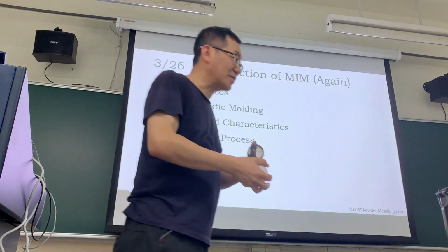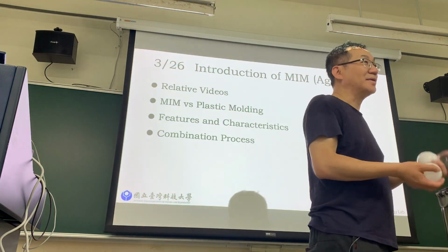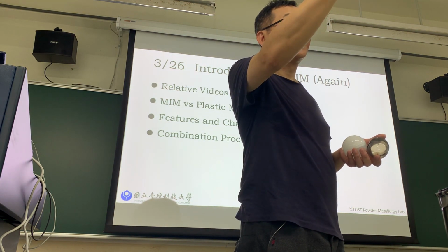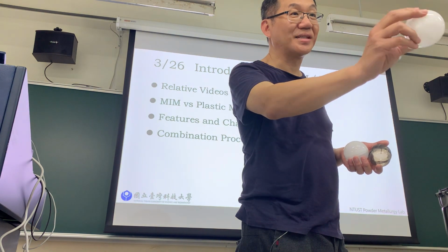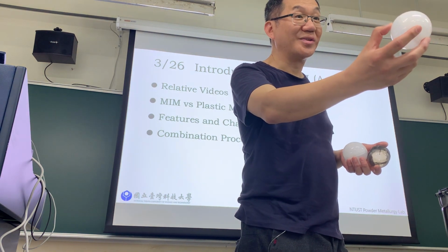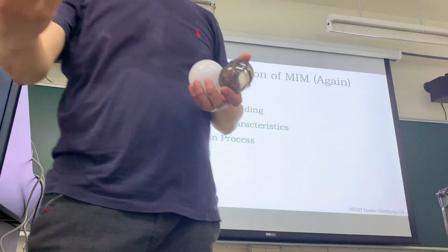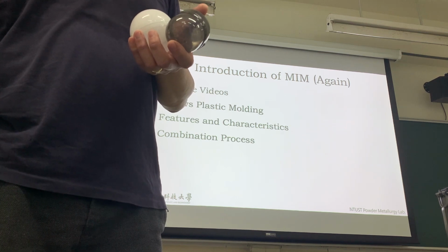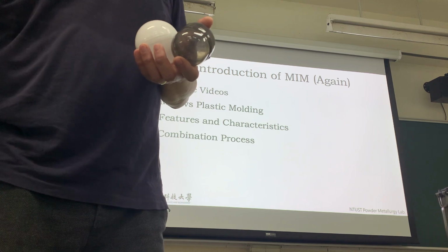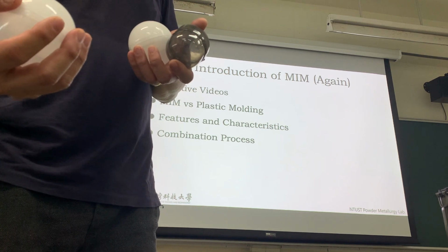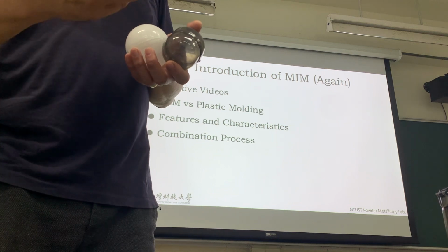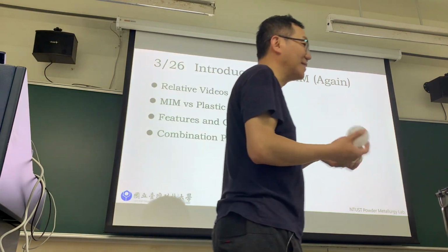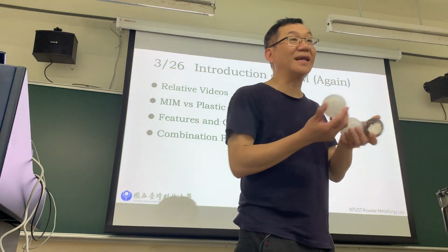Okay, so today we're talking about the powder. Ideally this is a powder. Am I right? Is this powder? No. Why? It's not like powder, because its dimension is too big. What is MIM powder size? Do you remember? 30 micron. Okay, 30 micron, that's right. So this one is just a shape like the powder.